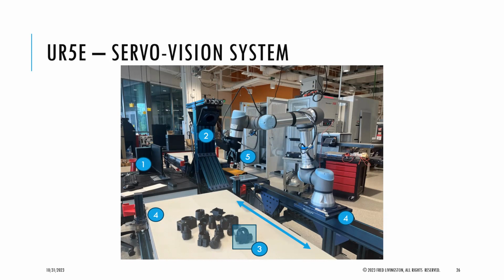This is where I'm currently at. My delta Q, my change in Q, is how much I need. So going from 0 degrees to 30 degrees is how I would program my robot to actually get to the target. So I'm computing the delta Qs, and then I could do a closed loop system on each one of the joints, and the robot would move to that location. And then I could just activate the gripper.